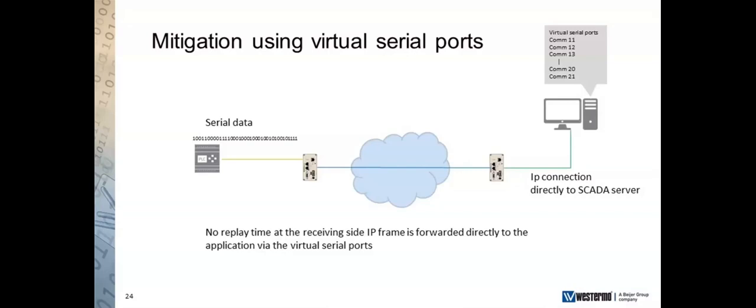When you move into the virtual serial port environment, you get away from that whole process of converting, at least at the SCADA end. You get away from the process of creating serial ports via terminal servers, and actually literally move all that technology up into the SCADA system. So you have a program which sits on the SCADA server, which emulates or creates virtual comms ports.